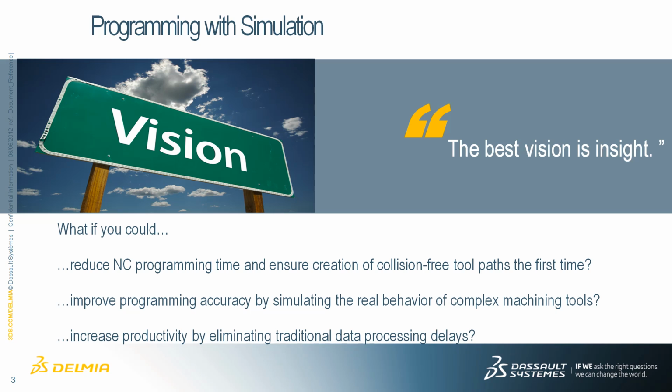For instance, validating the machine's setup, checking the machine capacity or reachability, choosing the right machine for the part, and most importantly, visualizing the machine behavior based on toolpaths and strategies used by the programmers. In other words, the toolpaths are generated considering the machine kinematics in V6.